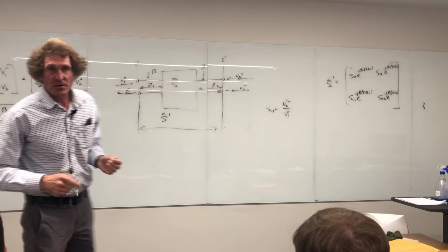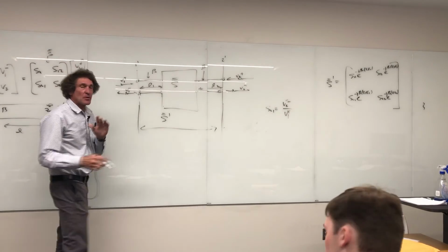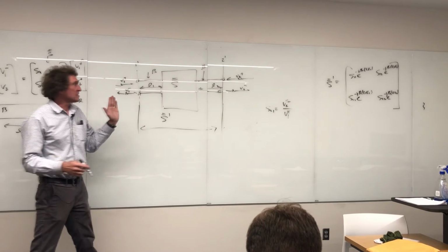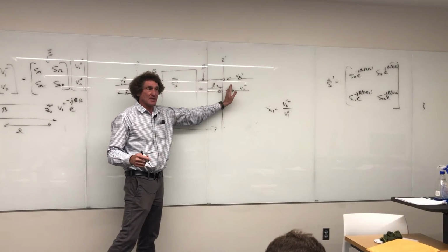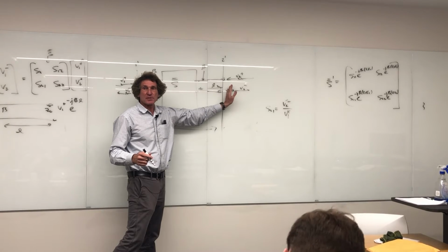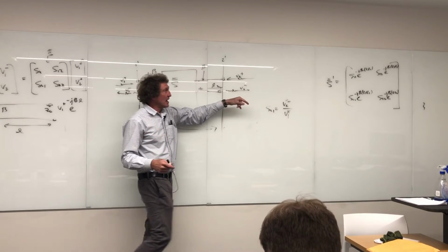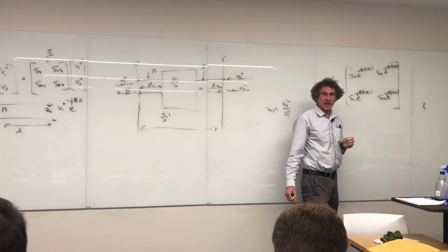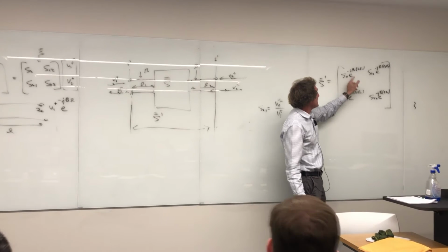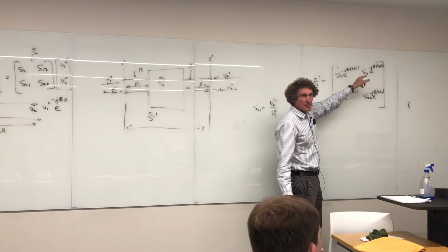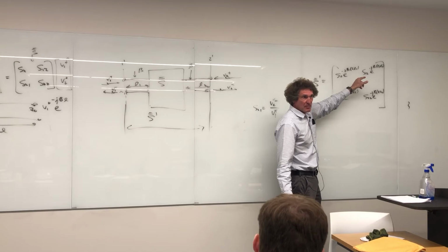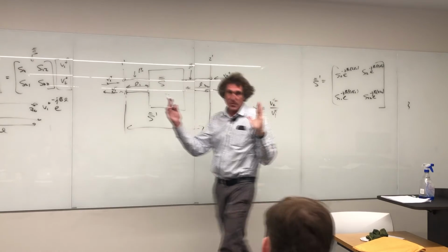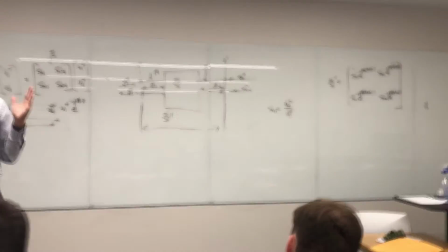Now, why do you need to do that? Because a lot of times, suppose I'm measuring the device, all right? And no matter what I do, I still need to connect by long lines to it. Well, then if I want the actual S parameters of that device, I have to eliminate these exponentials, I have to do an inverse of that. I have to multiply S11 times e to the plus j beta 2L1. Do you follow me? To get the actual S parameters. Everybody with me on this? It's just the inverse problem.